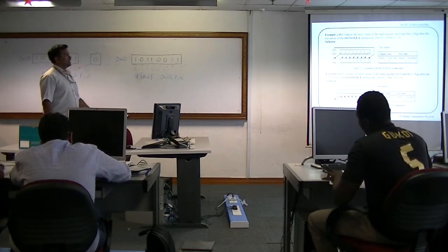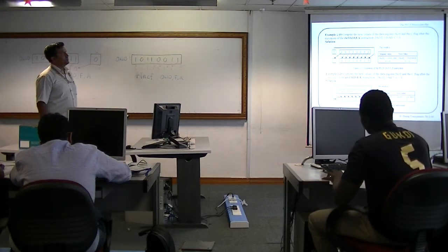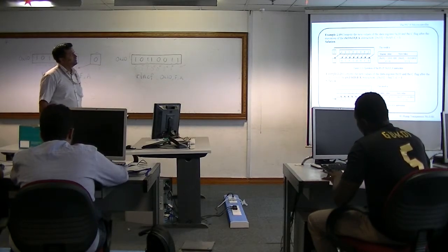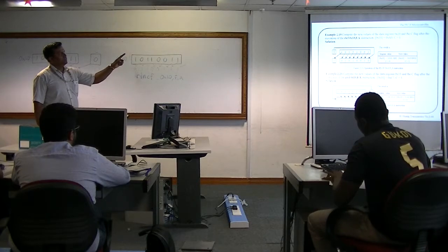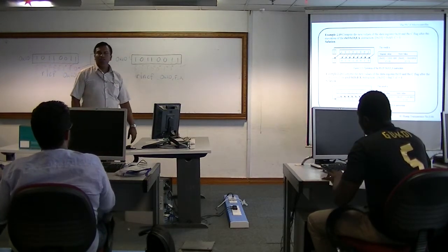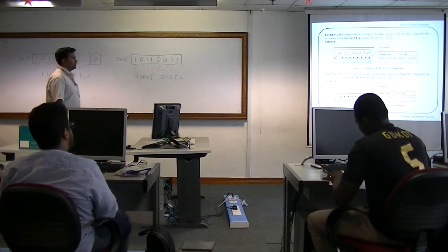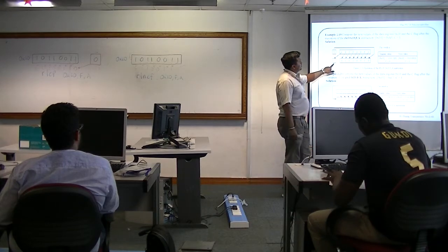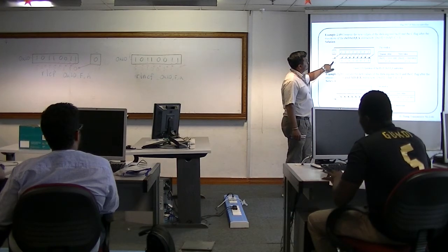Compute the new values of the data register hex 10 and the C flag after the execution of the rotate left hex 10 instruction, given the initial content of hex 10 is A9 and the initial condition of the carry bit is 1. So this is the initial condition.